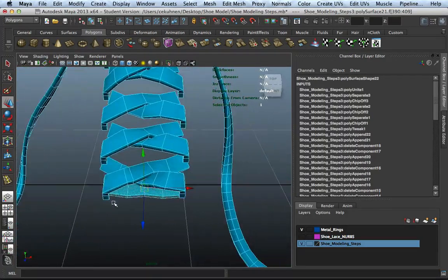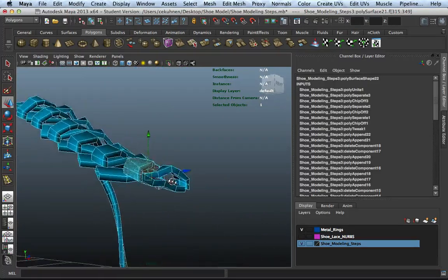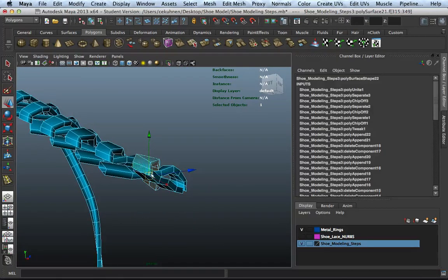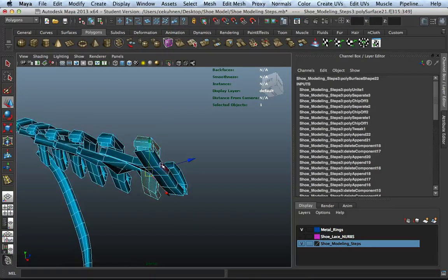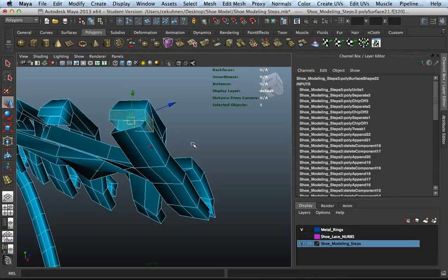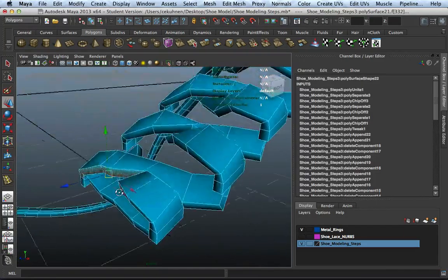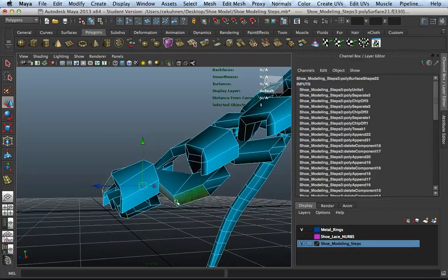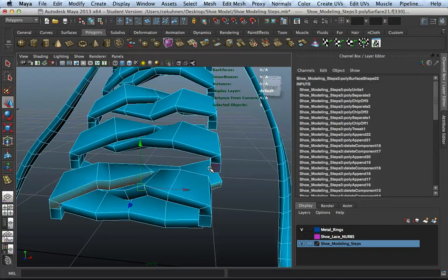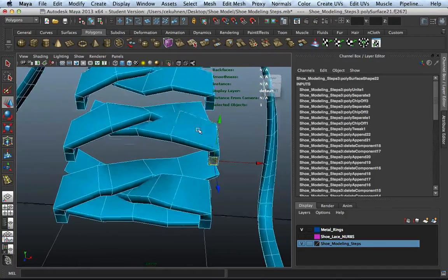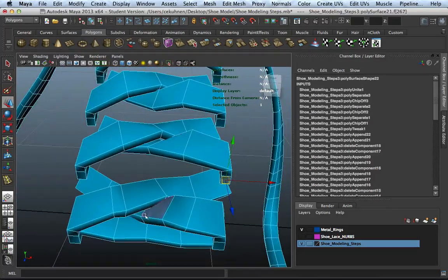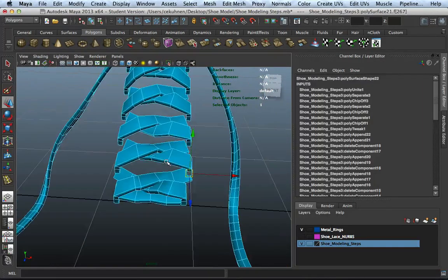Then to build those, I started with one cube at a side, which was my original cube. Then the top face, I started extruding out along this direction and always rotated the piece a little bit, copied and rotated the element to here, basically copy and paste, and then started to make slight mesh variations.